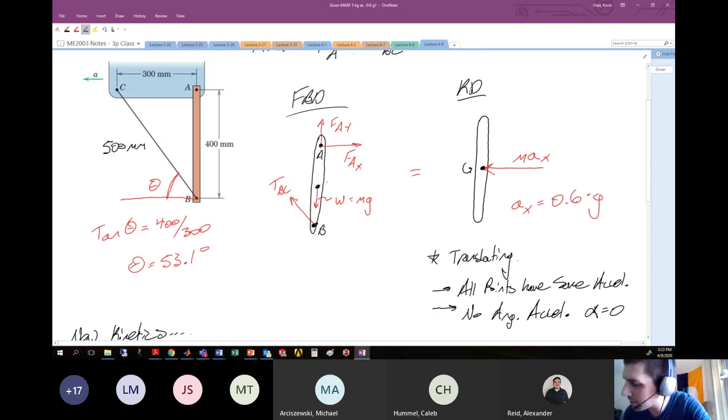And here we're focusing in on our center of gravity, which is this particular point here. So if I'm curious about the moments that act about that center of gravity, well, this force is not going to contribute anything to that because it's passing right through the center of gravity, so there's no moment arm. This guy also passes through the center of gravity, or is on the line of action that passes through the center of gravity, so he doesn't contribute any moment.